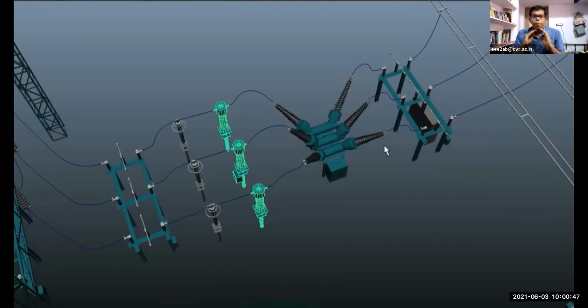Say, for example, there is a fault in the pole at your house. Three wires will be there, like R, Y, B, if you are connected with the 3 phase. Sometimes one wire may get loose or not be connected, so you will be receiving only 2 phase supply. In that scenario, the lineman will go to the nearby distribution transformer, DT, that is 11 kV to 415 volts.